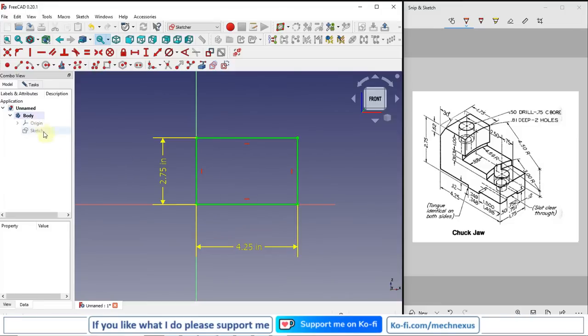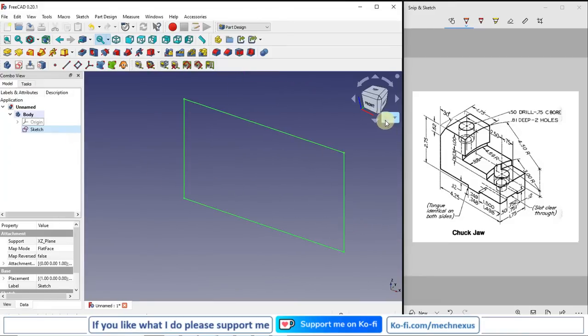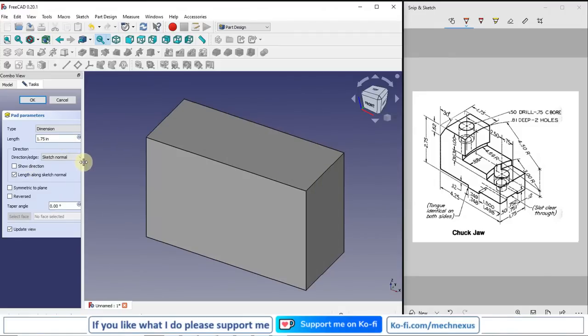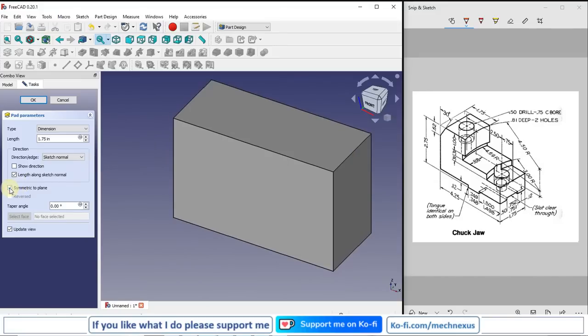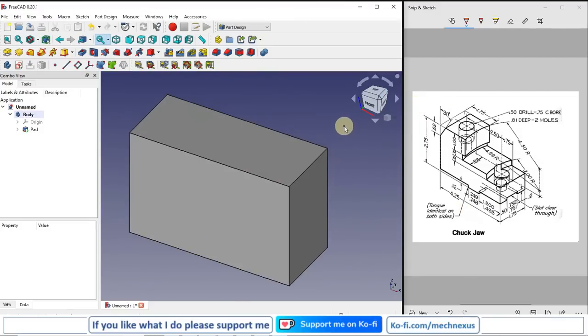And now we will make a solid extrusion. We'll close it, and a solid extrusion of 1.75 here, which we see in both the directions. So I will go for the pad and I will give here 1.75, and here I will go for symmetric to the plane and I will say OK. Now we have made our solid block.